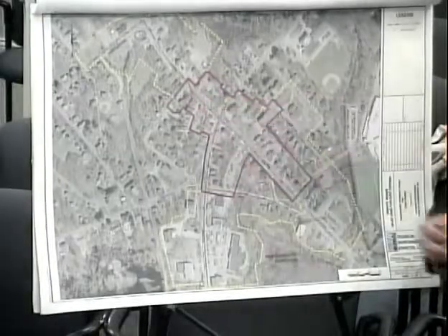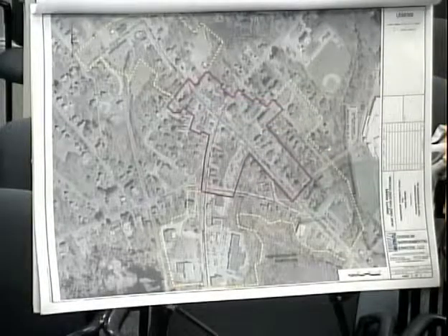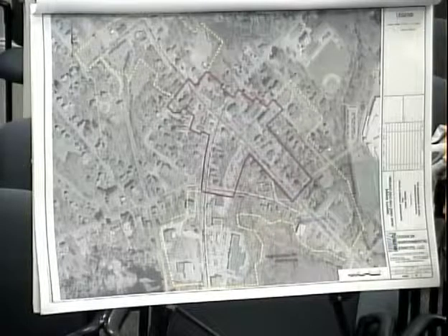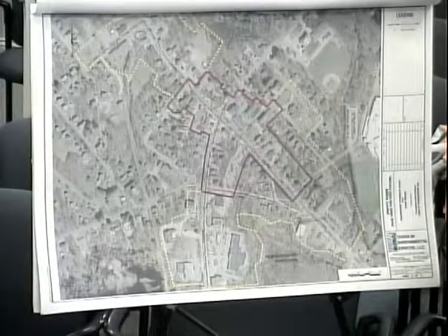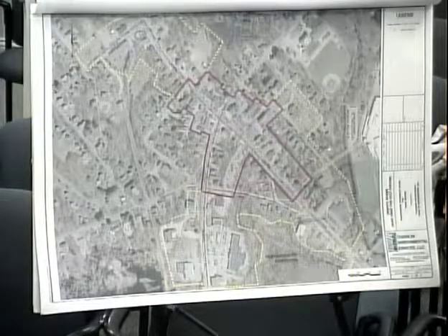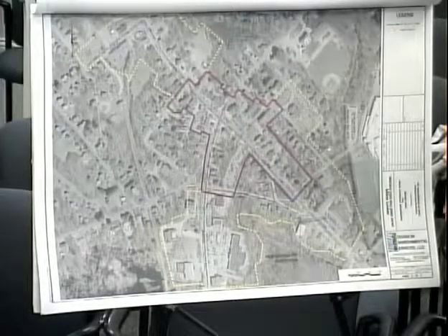These are your study areas. It's a little tough to see from there, but what we've done is basically outline a gravity collection system, and these are all 8-inch pipes that we're running through the streets. It's going to be difficult because you already have a bunch of utilities in the roadways: gas, electric, drainage, and water. So we have to find an avenue to get there, and generally speaking, that means the sewer goes down.